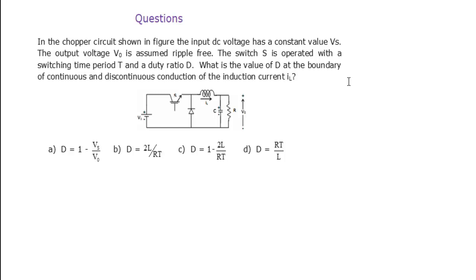So first we need to look at what circuit diagram is given. Okay, this question is related to SMPS. In case of SMPS, in the last slide I told you how to identify whether the given circuit is a buck converter or boost converter or buck boost converter. For that we need to look at the inductor location. Is it on the source side or is it on the load side?